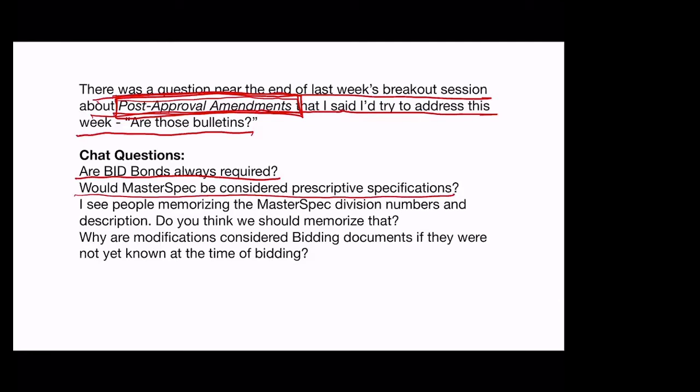Master spec is not so much the type of specifications, it's more like the cataloging system. If you're old enough to have been taught this, it's like the Dewey Decimal System for cataloging books in the library. Just because it's in master spec doesn't mean it's a historical fiction book. It could be a fiction book, or a nonfiction book, or a self-help book, or anything. It's just cataloged in a certain way where the contractors and subcontractors and you, the architect, know where to look for something. So if you wanted to know whether it was 277 volt power or 120 volt power that was going to be delivered to the building, that's the kind of thing that would likely be in the specs.